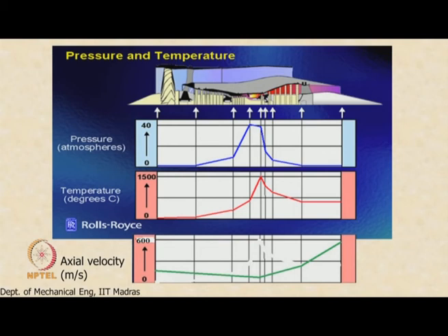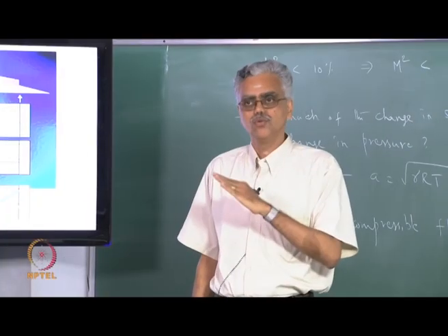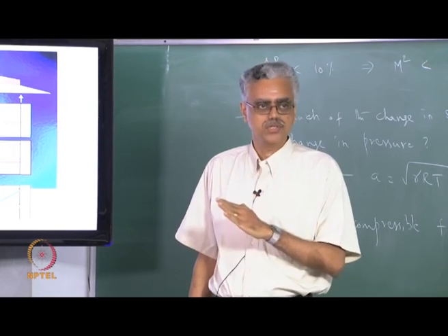Not only will the temperature increase in a ramjet or a scramjet engine with addition of heat, the pressure will also increase. So that tells you that the change in specific volume is also due to a significant change in pressure, which means when we go to a ramjet or a scramjet combustor, we need to account for compressibility effects in the combustor.